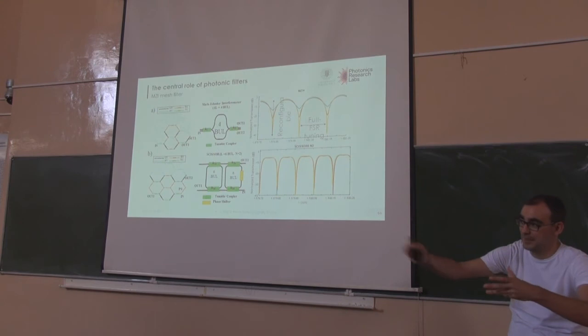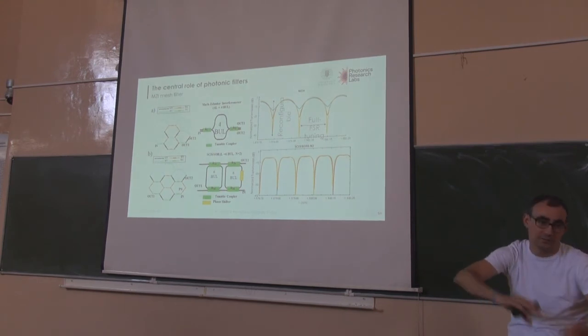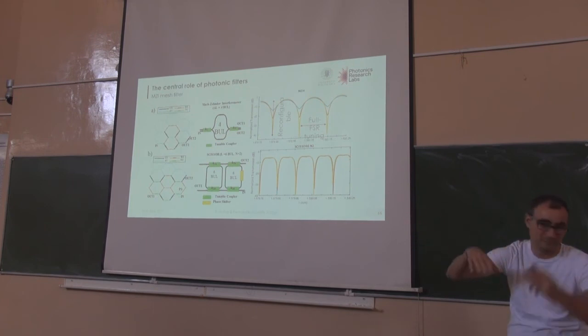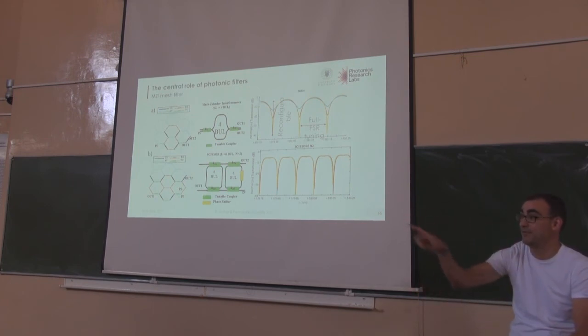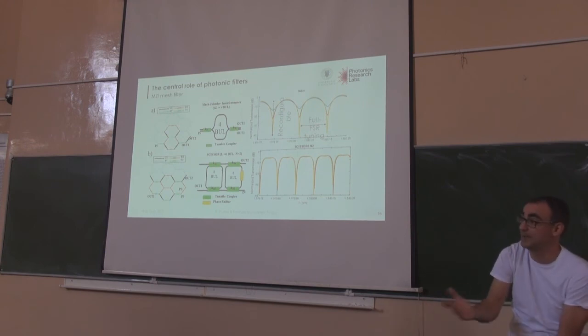The first step is to learn how your circuit is after fabrication. Of course, not all are in bar, not all are in cross. It's a little bit arbitrary, because it's optical phase, and that depends on the roughness of the waveguides, and that is something unpredictable.